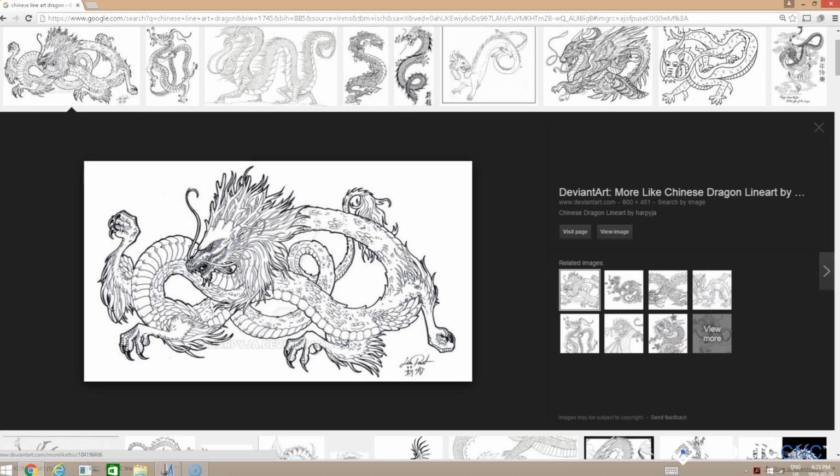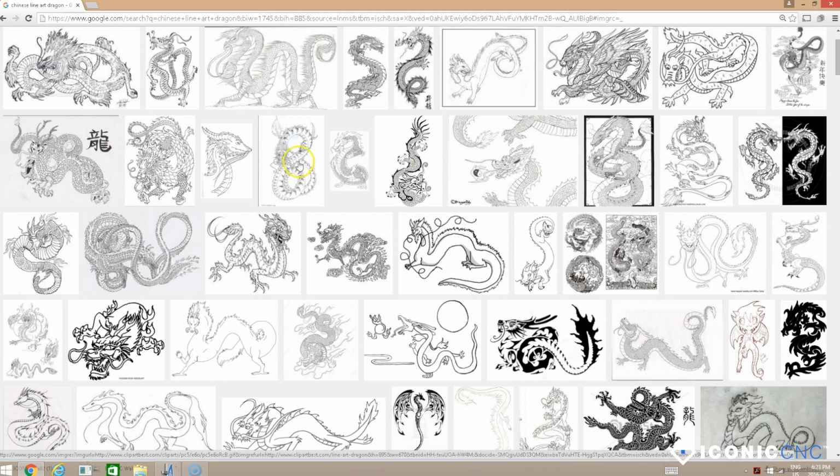If you're trying to get very, very fine detail, the machine assumes the material thickness to be flat, and if it's not, then you're going to get some areas that are over machined, some areas that are not machined at all. So you have to be very careful with things with fine detail. As you get more experience with your machine, you find ways around that. I've done several projects with very fine detail and basically over machined the project, and then by just using a palm sander, sanded down the areas that were slightly over machined till I got the result that I wanted.